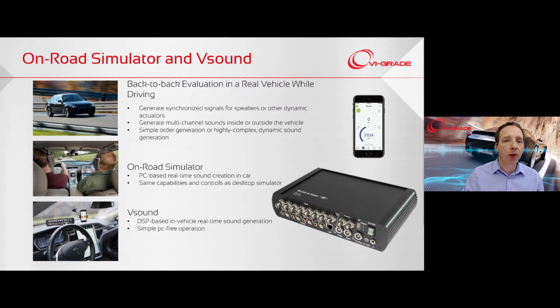The on-road simulator and Vsound enable the playback and experience of vehicle models made with a desktop NVH simulator in a real car interactively while driving, with sound synchronized with and generated in real time based on real-time vehicle parameters of engine speed, road speed, pedal position, and so forth. This provides the most immersive environment for evaluating sounds.